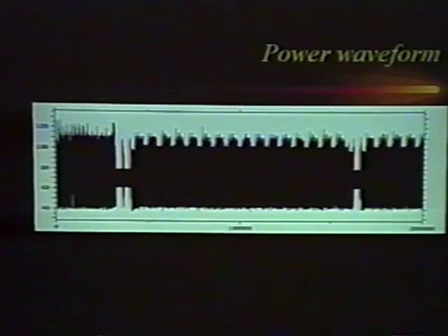Now, the number 16 means a lot to cryptographers. In this case, we know that the smart card is running the DES algorithm. We are looking at 16 rounds of DES. So here we are at the stage that we can recognize the processes in the software. We can pinpoint the exact timing where processes take place.